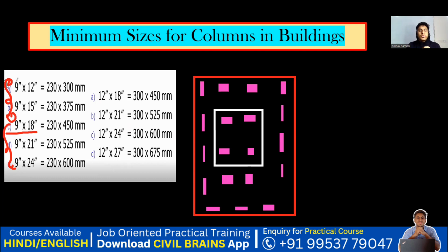Agree with me? So I'll go with 9 inch by 18 inch for this. And all my exterior columns, since less load is coming, I can go with 9 inch by 12 inch. Again, you need to do a proper analysis, but as a rough thumb rule, you can give all your outer columns 9 inch by 12 inch.